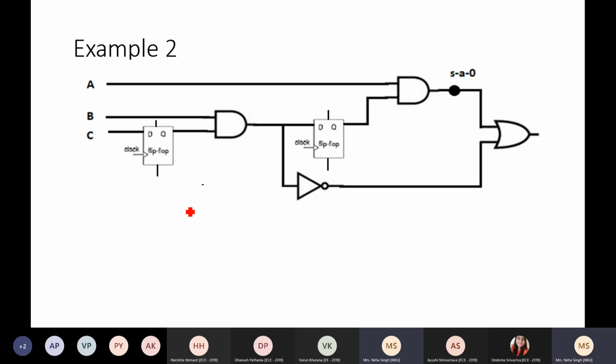This was the circuit that we did in the previous class when we were talking about the normal testing for a sequential circuit using the time frame method. Now if I have a set and a reset pin added to my D flip-flops, what is the ease that I get? If I want to transmit this fault stuck at 0, it means actual value is 1, faulty value is 0, so a D is seen here. This fault D will be propagated only if I have the value here as 0.